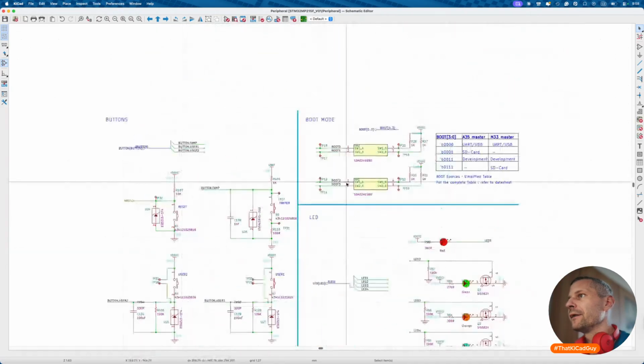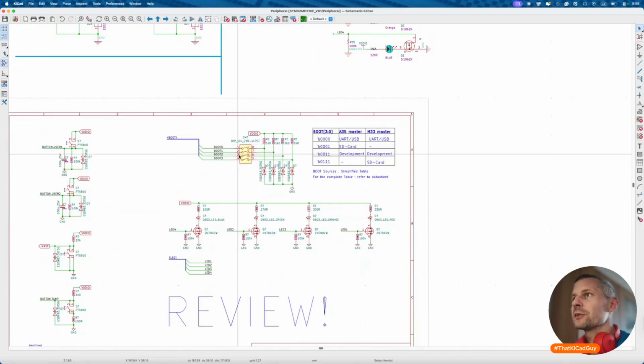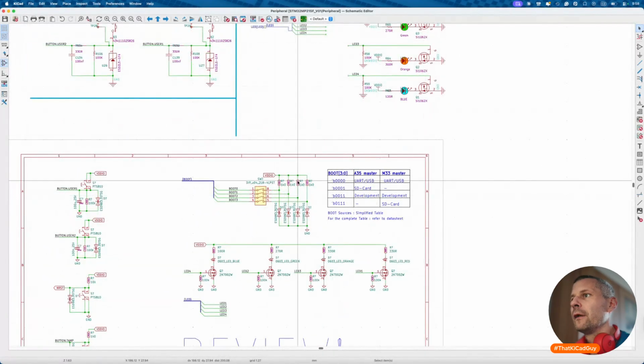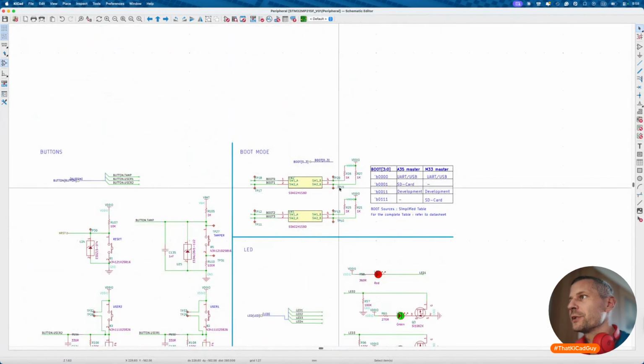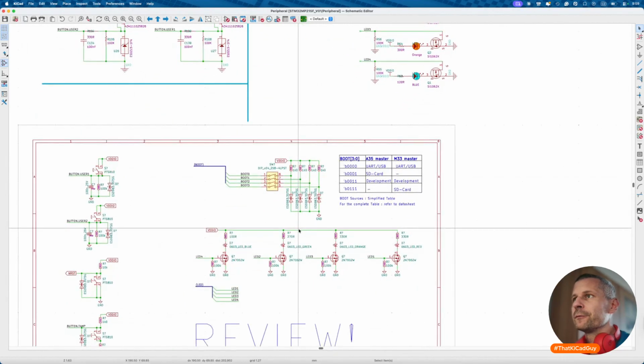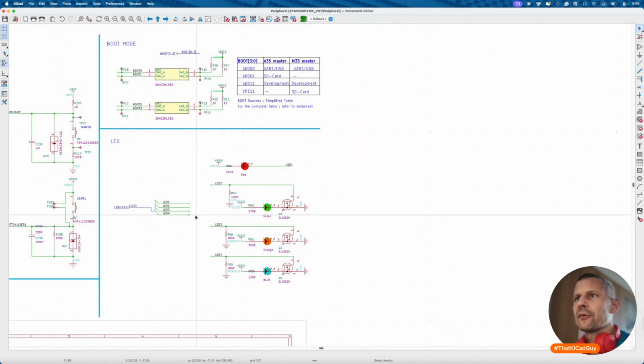label. Then there is a boot mode selector containing 2 dip switches. I used the 4-pole one, ESD. Every signal, boot 1, boot 0, 1, 2, 3, are pulled up to VDD IO. I added ESD protection because it was missing. Here is a table describing the meaning of the combinations.